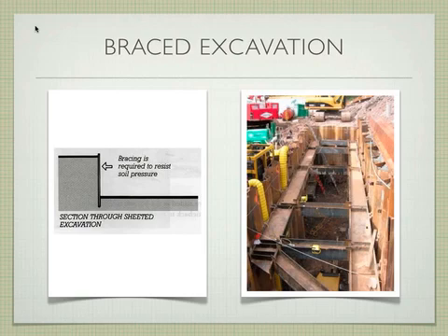And a braced excavation generally means that you're going to dig straight down, and somehow you're going to support this wall from caving in on your particular site. So you have to think about that positioning and how you're going to brace it and what kind of impact that has on the site when you do it.